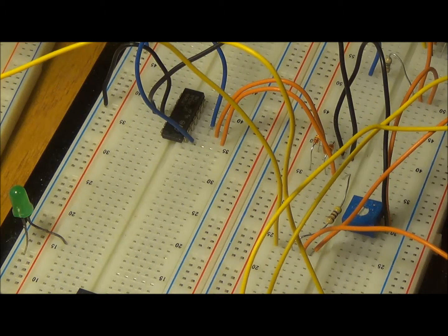So when the voltage exceeds 0 volts, the op-amp output will saturate to 5.2 volts, and when it's 0 or below 0, it will remain at 0 volts. And that's how I get a square wave, and that's a way of detecting when the zero crossings are happening. Now I'll turn the oscilloscope on and I'll show you how this works.